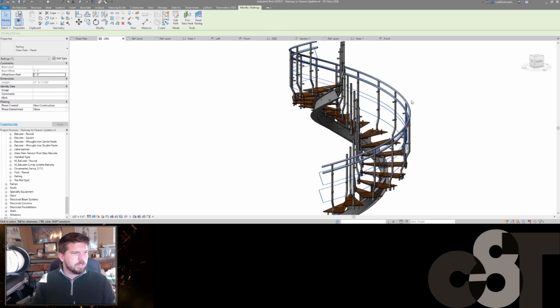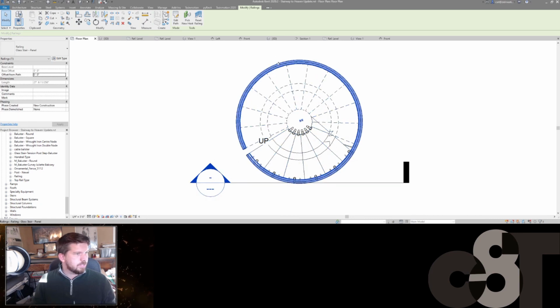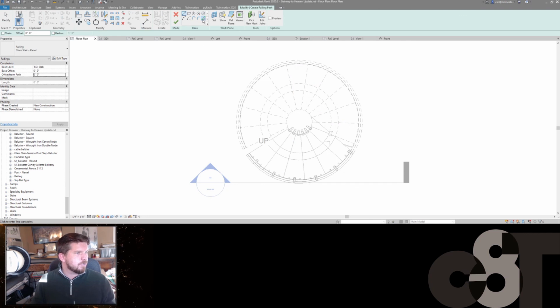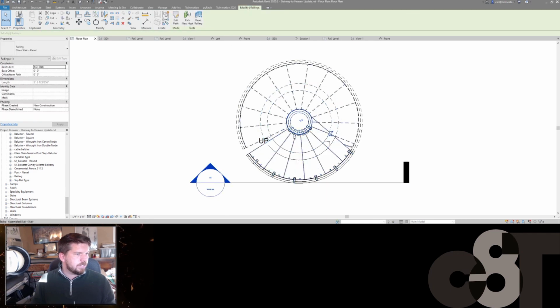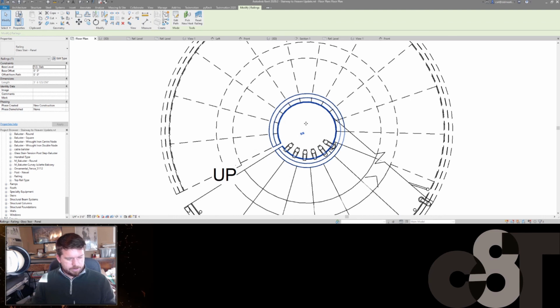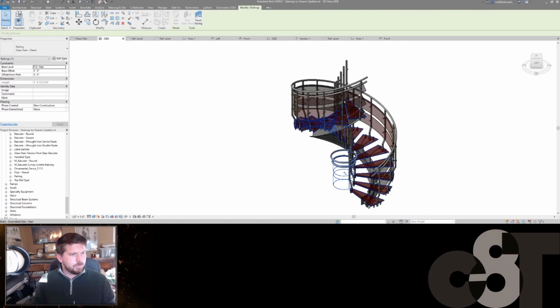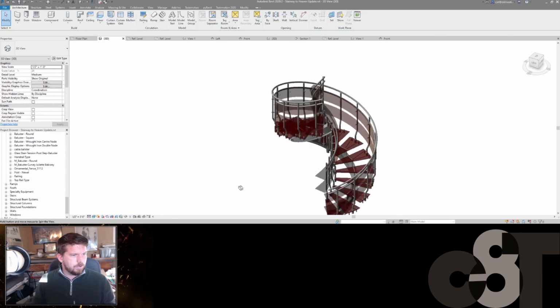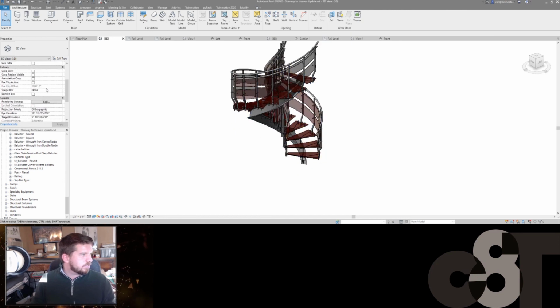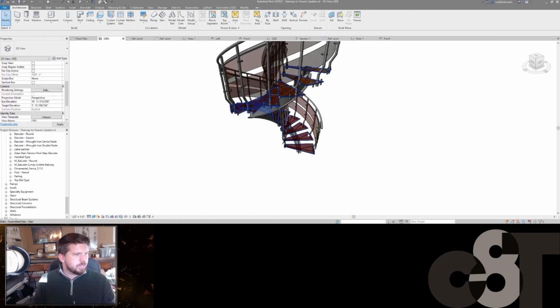And then we're going to create a railing on the other side. So let's go back to floor plan and let's create similar. So you can right click that and hit create similar, or you can just hit CS as a keyboard shortcut that I've got. And we're going to create a railing right here. Wrap that bad boy up and finish that. And I think we need to flip that. And there is, oh, almost our stair. Maybe we should tell it to use this stair as its host. There we go.